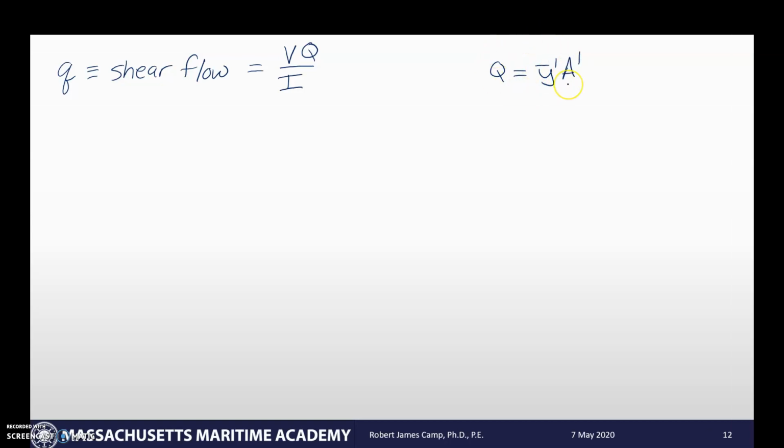This comes in critical when we're looking at forces on fasteners, because remember what we've talked about, Q is kind of the area that is driving the amount of horizontal shear stress in an object. And for shear flow, that Q value is really going to be the area that's driving the force on the fastener. Okay, and so once again, you'll want to box your equations. This one right here, the shear flow one, is important to box. It's a pretty simple equation. There's not much to it.